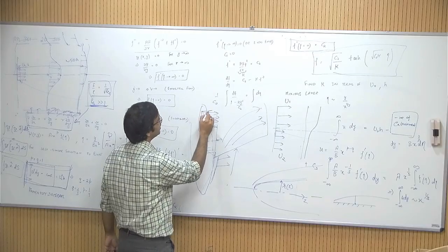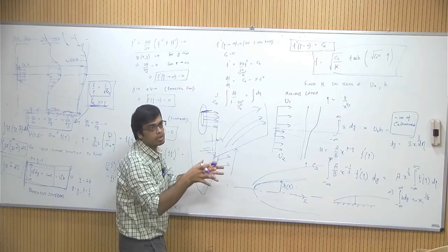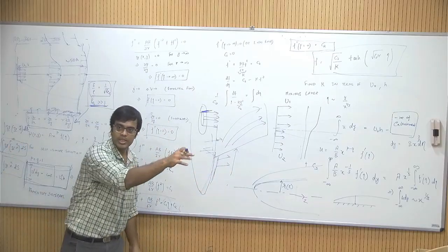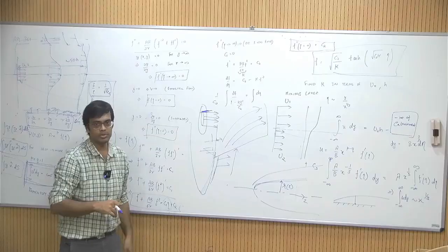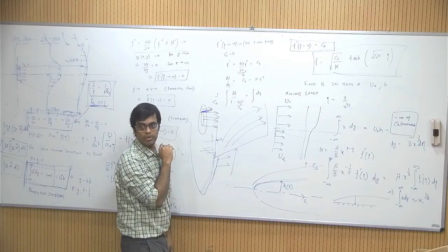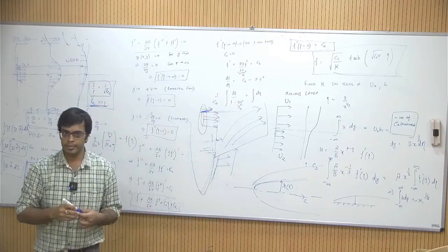Okay, that flow is because of some bypass that was done in your jet engine. So bypass is basically not all of the air is used to do the combustion in the combustion chamber and spin the turbine. Some is used for cooling and all of those things. That bypassed air will be flowing from the outer annulus. So you will form a mixing layer type of situation here.